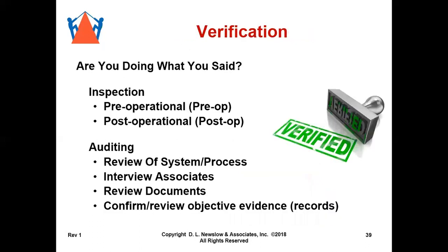Verification. Are you doing what you said you're doing? That's what verification is about. What do we say we're going to do, and are we doing it? So if we say we're going to manufacture at 151 degrees for 16 seconds, then that's what we're doing, and we have records to show it. We review the system, interview the processes through auditing, review documents, and review objective evidence such as records. That's saying you're doing what you say you're doing.